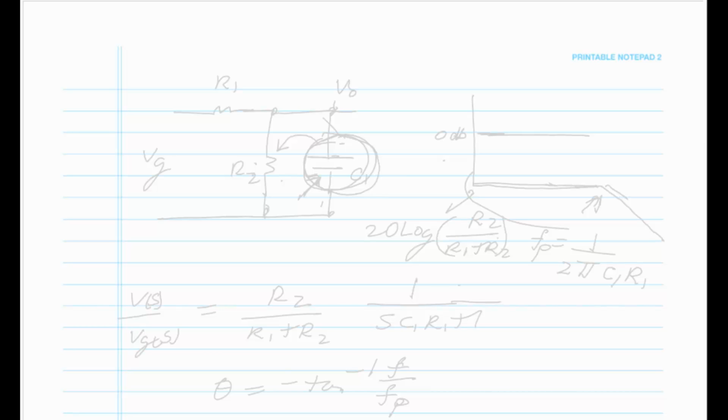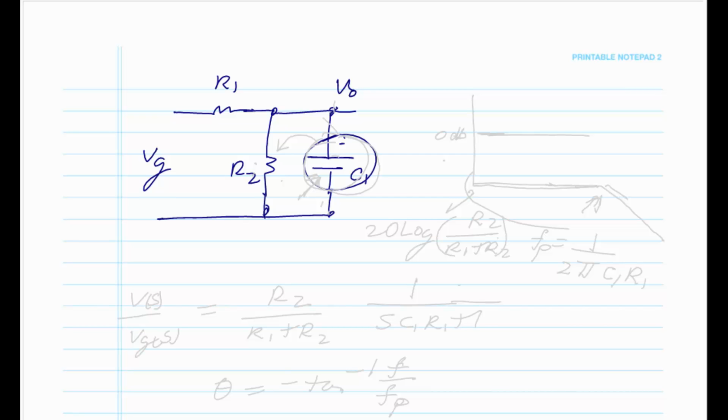So the next thing we want to look at is to say, okay, well, how about some kind of other signals? We have an R1, we're going to have a R2, and now we put here, all this is similar to the first circuits that we did, but the only difference here is at DC this capacitor is an open. This capacitor is an open at DC. And we just have a resistor divider. So the only thing we do is we're starting off at a different value here of, basically, if this is the angle of 0 dB, we're going to start off at R2 over R1 plus R2. That's the DC term. And we do 20 log to get this in dB. And then this is the starting. This is walking the frequency. This is the low frequency, meaning that at low frequency, this impedance is infinity. Infinity in parallel with any resistor is that resistor.